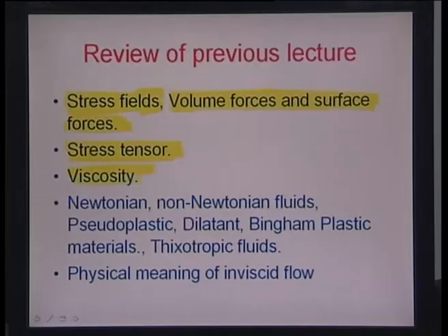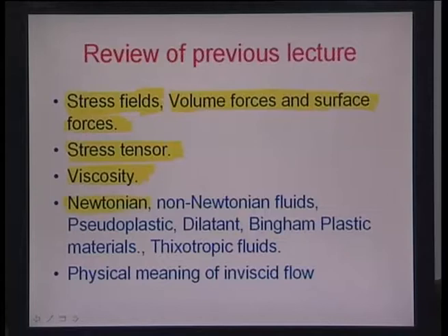We tried to derive the basic Newton's law for viscosity, Newton's law for viscous motion of fluids, wherein a correlation was drawn between the shear stress tau xy and the rate of deformation du by dy, and we classified different fluids as Newtonian and non-Newtonian.